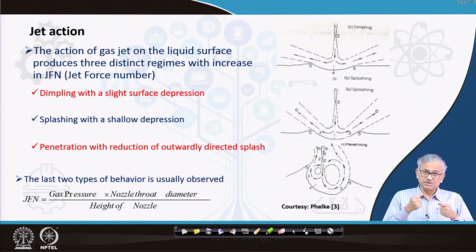So if GFN is very high and the carrier is very big, in that case the rate of decarburization can be more than that of the FeO formation, and that condition gives rise to the drying situation, drying of the slag, and that is called the hard blow, right? That is called a hard blow. And people sometimes do it only to increase the decarburization to a much faster rate. Okay, otherwise it is not justified.